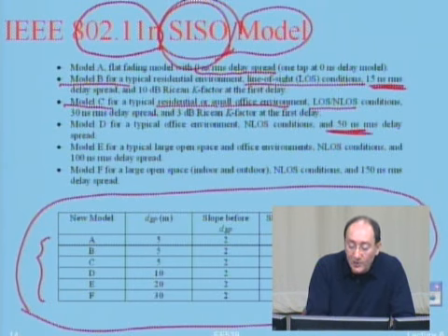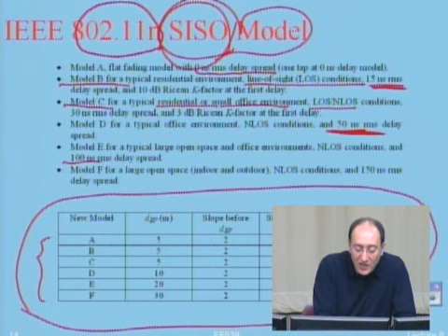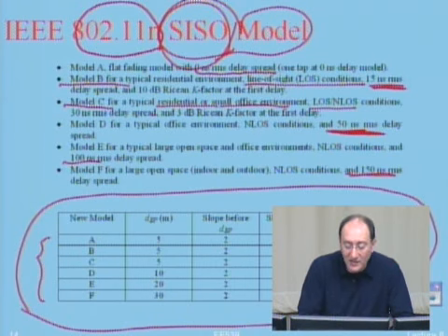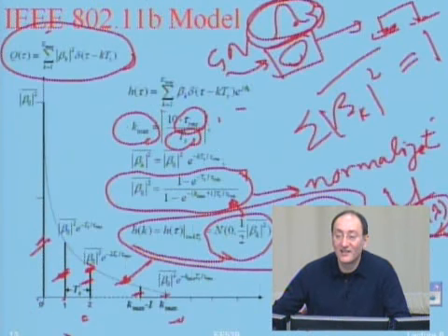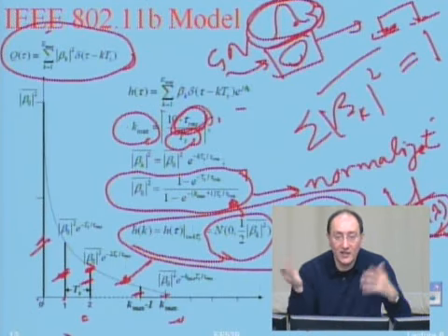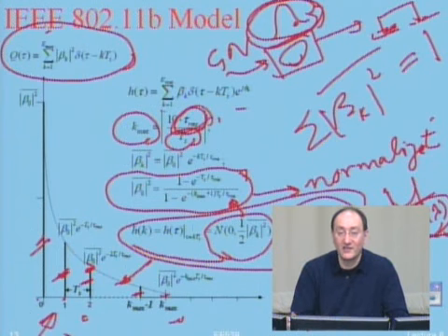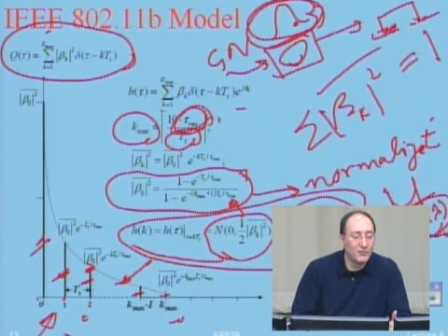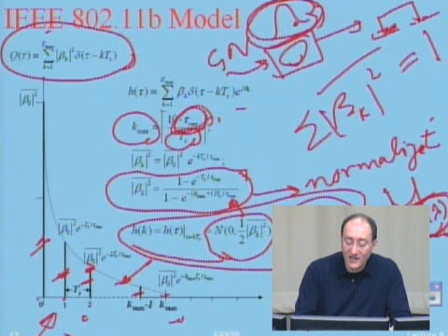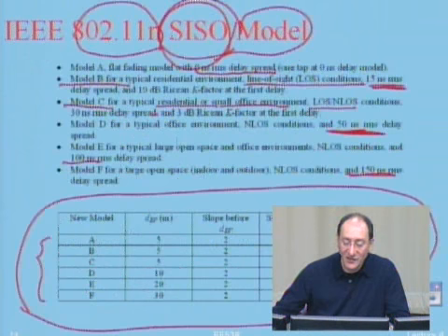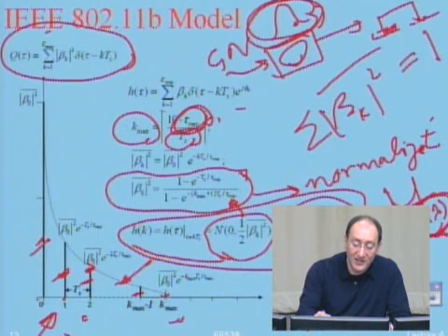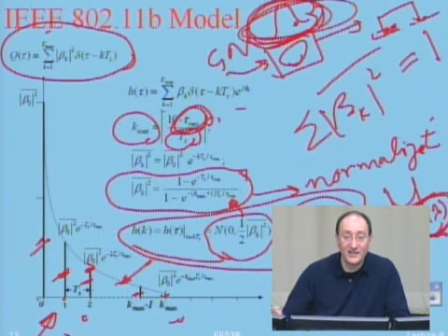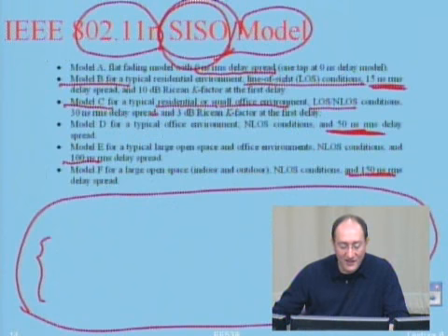But anyway, this is the important one: the delay spread that they associate to each of them. These are the associated delay spreads. Okay? Now, you get these delay spreads, you can substitute them into what? Into the RMS in the previous page. In this guy. Here we are. I have the channel profile for all of them. Now, what is left? One is d sub lambda and the other one is the path loss model. For d sub lambda, they suggest a filter like this and we are all set. So I need only the path loss.